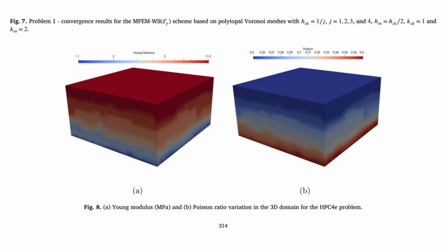Okay, let's build this up. The basic problem we're solving is linear elasticity. And that means we're usually tracking two key things, right? Stress, which we call sigma, and displacement. That's right. And often we set up the math using what's called the Hellinger-Reissner formulation, but that immediately throws up a couple of big roadblocks. Roadblocks, like the cost we just mentioned. Yes, cost is one. But there's another more subtle mathematical issue that pops up, something called locking phenomena.